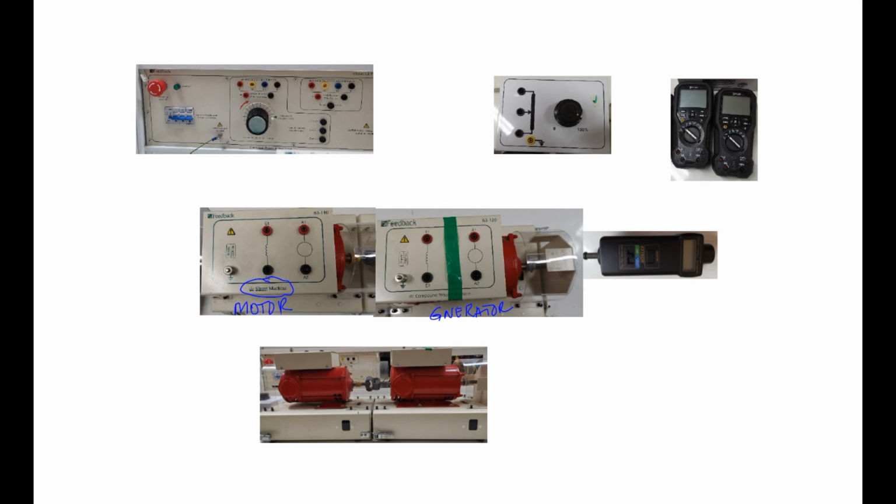And this is a side view of our coupled machines, and you can see the mechanical coupling, done using this mechanical part to connect the motor and generator together. So once we excite the motor and we change the speed of the motor, this will be carried by this rotor here. That rotor will be rotating the other rotor, and the generator will follow in terms of speed. They will have the same speed.